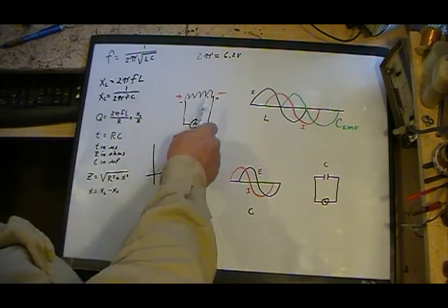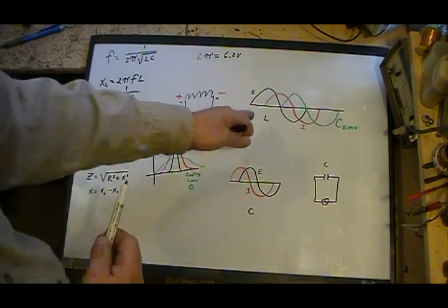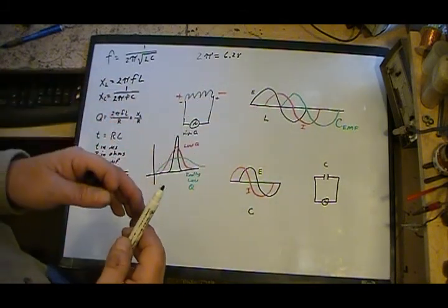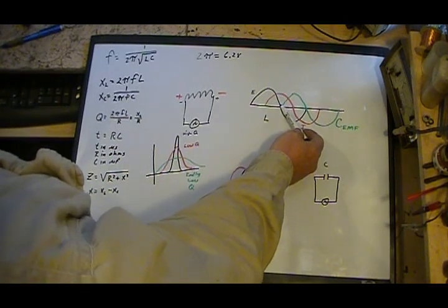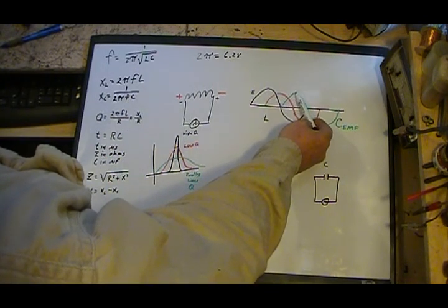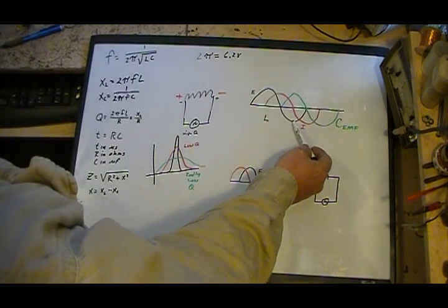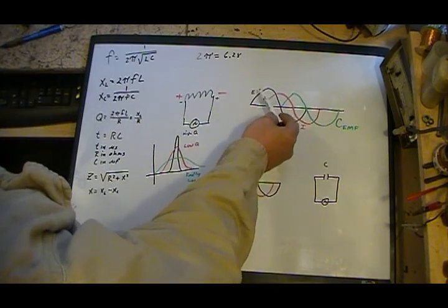Well, there's one other thing that goes on in these coils that helps cause the lag in I, and that is the counter EMF. The counter EMF starts showing up at about 180 degrees and flows up and back down at pretty much the same level, within reason, of your initial voltage that you're applying.